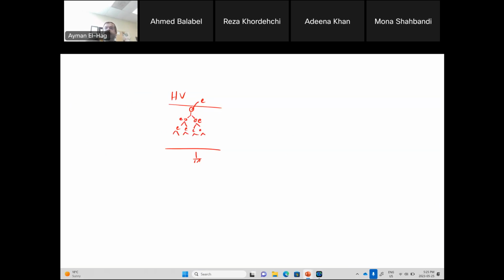Now this process takes some time to find the electron that will initiate the process. The faster your stress is, the more likely that you will not have this electron. So you might increase the voltage without finding the electron to start the avalanche.